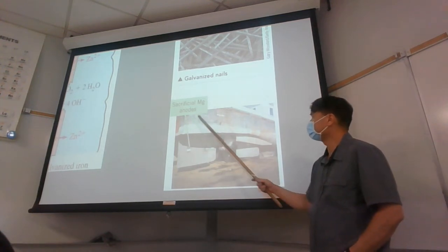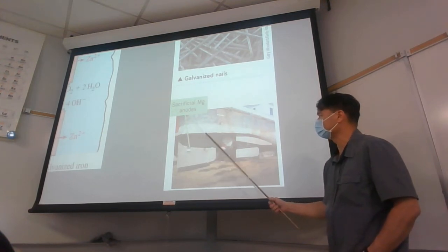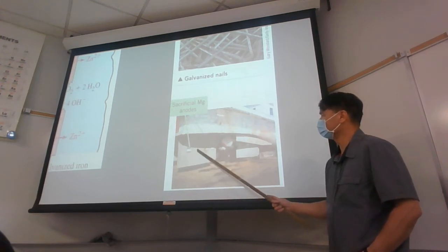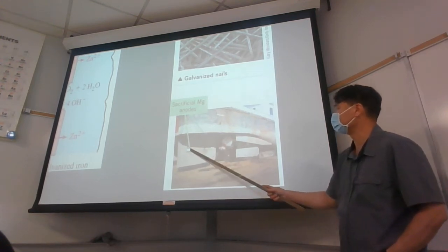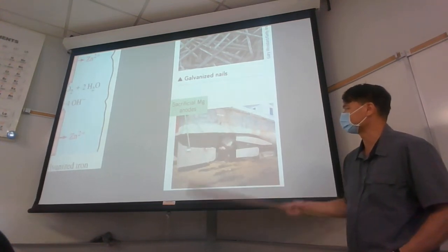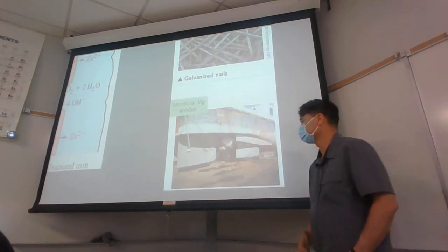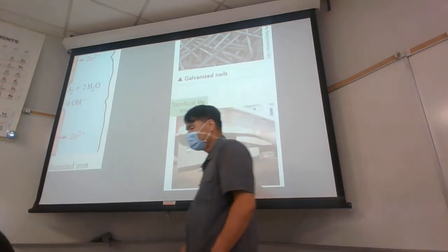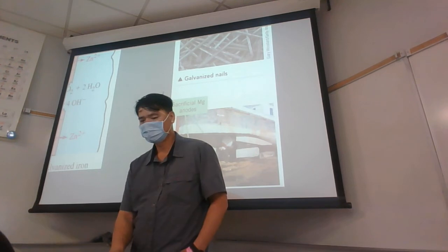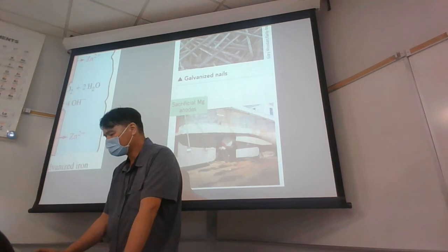Here, we aren't going to have enough sacrificial anode to protect them both. And so they have replaceable units here. These are sacrificial anodes of magnesium. So magnesium versus steel, magnesium has a higher oxidation potential, therefore magnesium will be oxidized. Once that's completely oxidized, then you can replace the sacrificial anode, as we call it, and generate more protection for the steel. You can buy sacrificial anodes at Home Depot for plumbing systems, that kind of stuff.